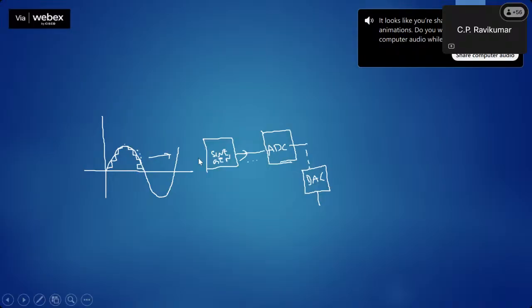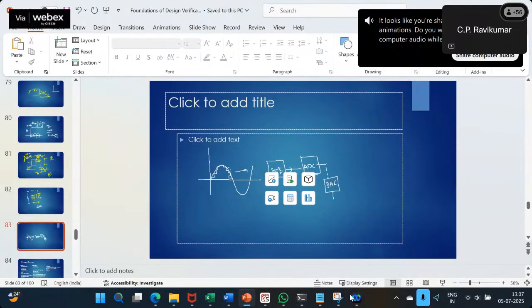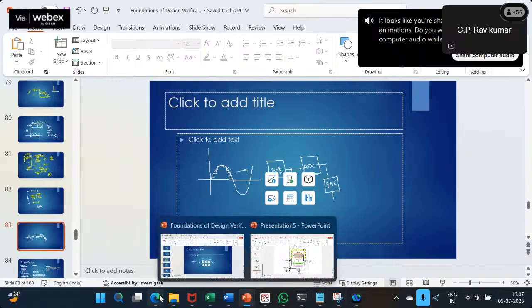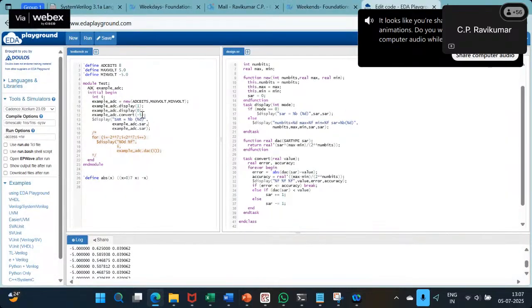So instead of converting random signals, here I have just taken some random values, like -5, etc. But you could write a loop here. Okay, so I will leave this as an exercise. Generate values of some sinusoidal waveform. You cannot exceed 5 volts, that's the only thing, right? If you exceed 5 volts, the ADC will not work correctly.